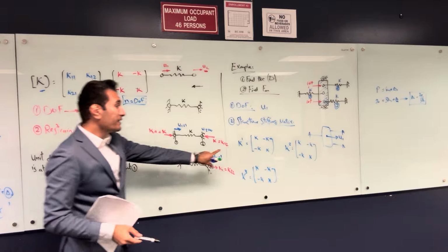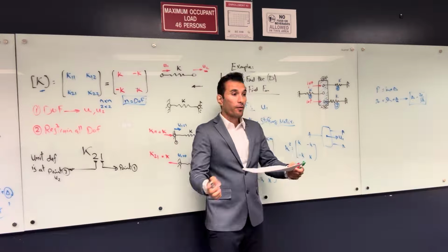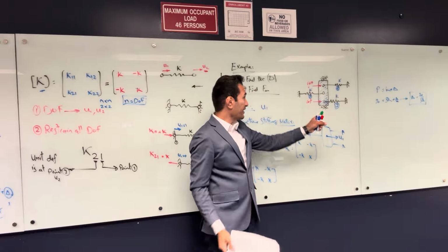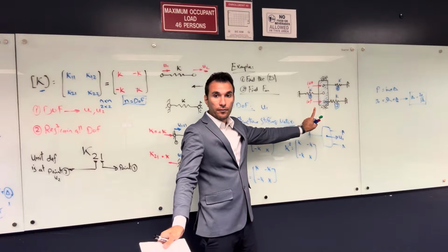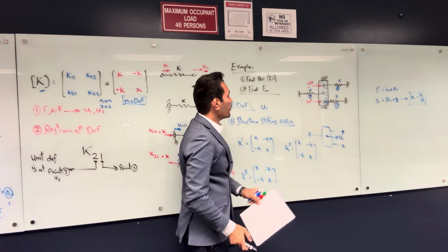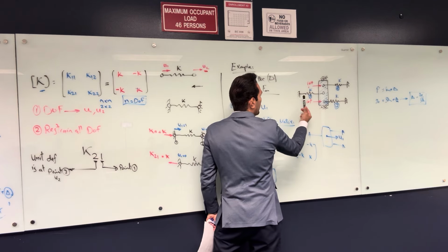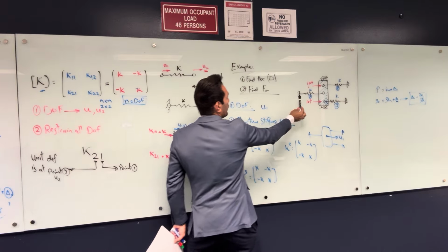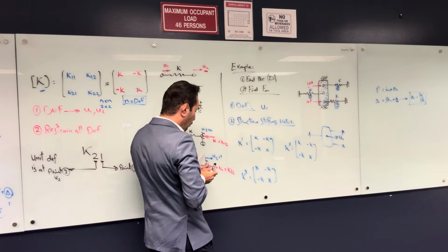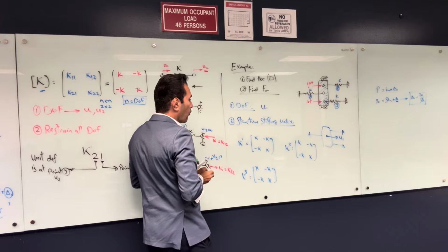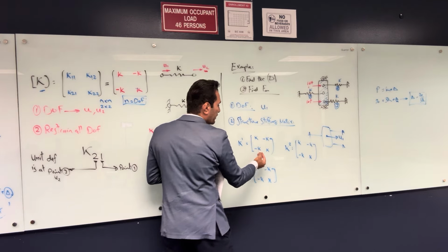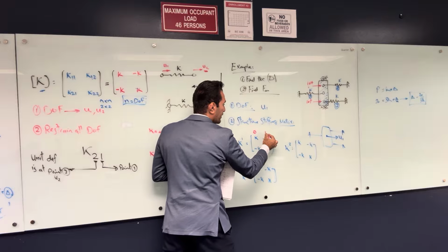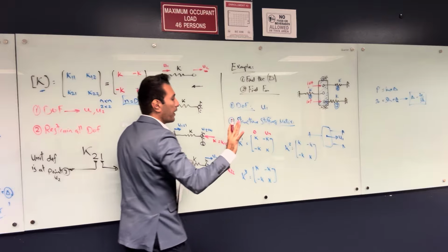Okay, so that is the stiffness matrix of a member, assuming that both points are free, right? But in this structure, are they free? They are not free. It's free from one end. So which end here is free? Look, this is U1 and U2. U2 is the one that's free. So that's what we do. Because this column is coming from U1, this is gonna be 0, and this is the one that has U1.